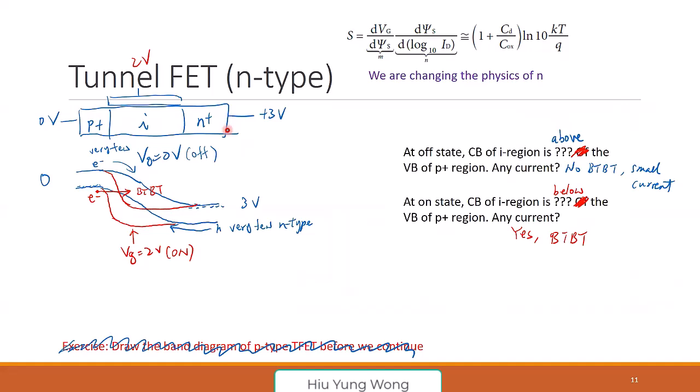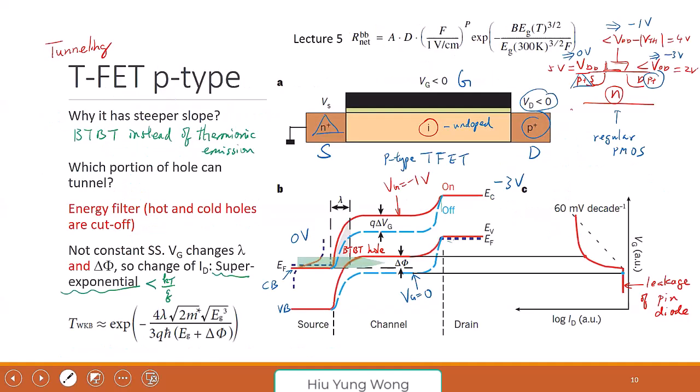And they don't work usually, but because we try to use the band-to-band tunneling effect, what we did is use the gate voltage to modify the band so that we have a very narrow tunneling region. Suddenly, a lot of current goes through because band-to-band tunneling is turned on. And due to this super exponential, remember the WKB approximation, you don't need to derive it.